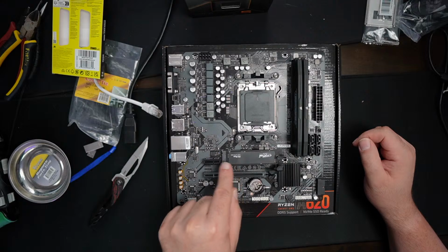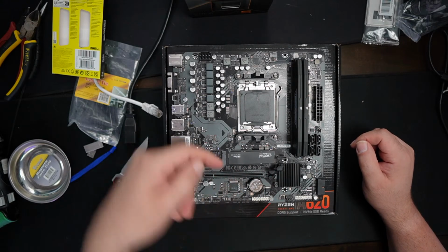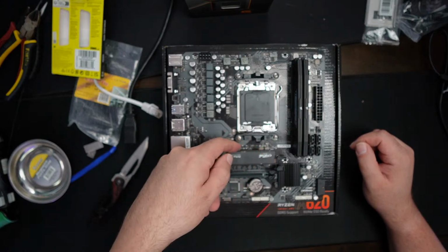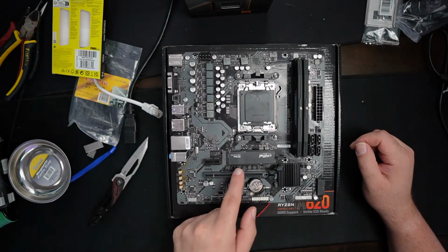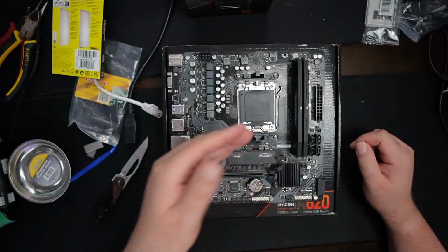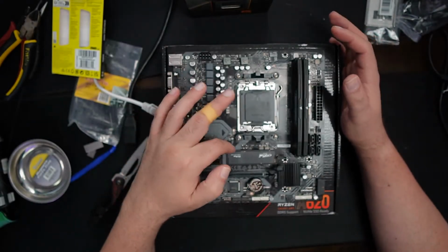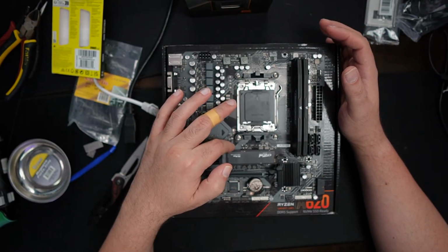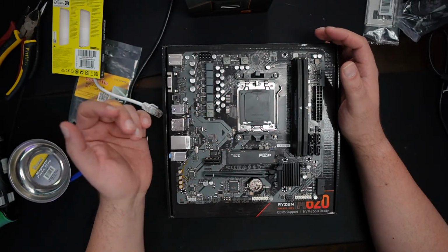Now, it's going to be flat, but it's going to be flat to wherever you just plug this into. It's not going to be flat to the motherboard. You're going to have obviously some room between the NVMe drive and the actual motherboard. This is on purpose. This is to get airflow underneath the NVMe drive. This is normal. These drives do get pretty hot, so you do need some sort of cooling in there, and that's pretty much the only cooling that it gets.